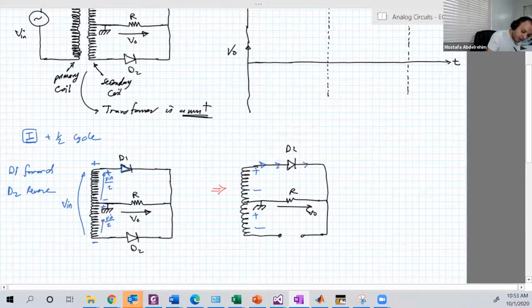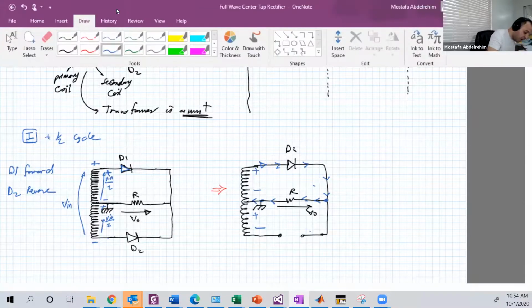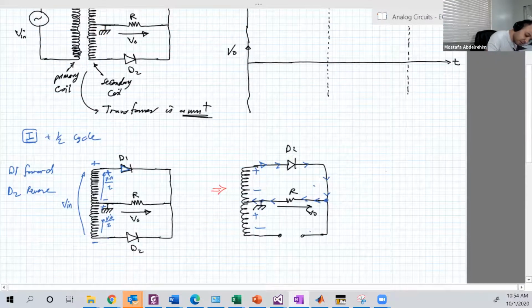And before continuing, this is a valid direction, because when this diode is on, it only allows the current to flow from B to N. Then it comes to this node. This is open circuit, so all the current will go to the resistor. And notice the direction. It's flowing right to left, from this node to the ground, and continues to the negative terminal. So basically, we can remove the lower half. It's just a model.